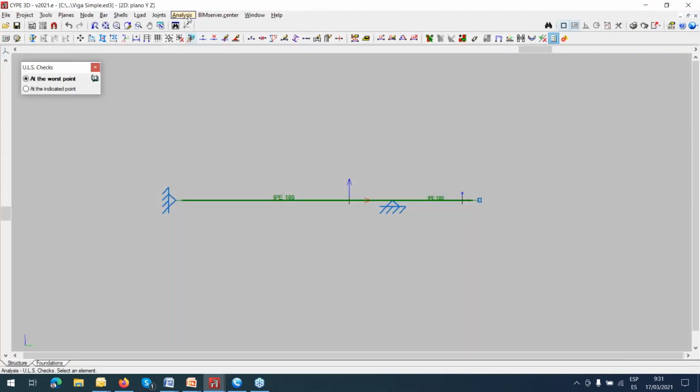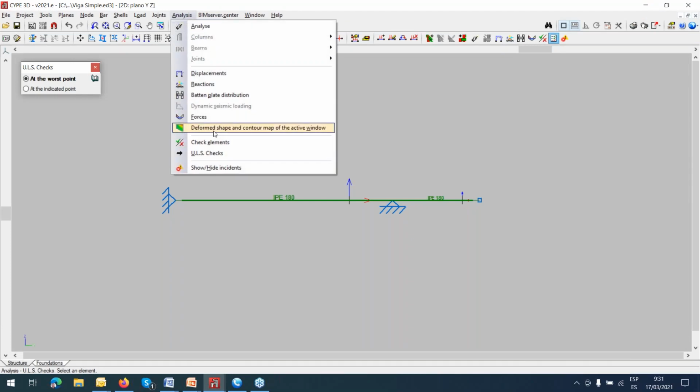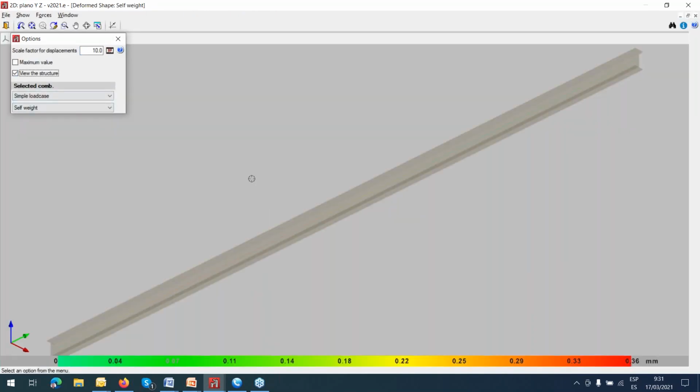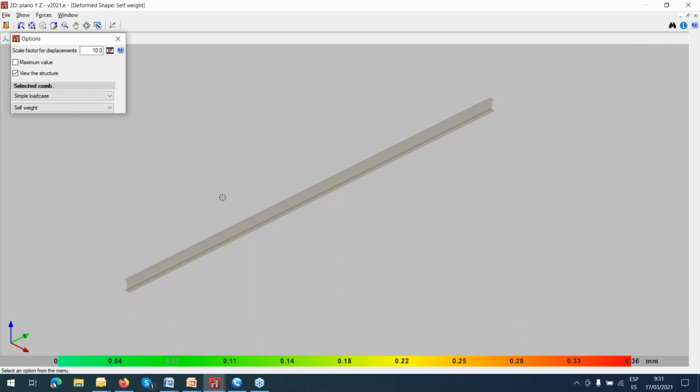And also, for the second analysis, you can visualize the deformation of the bar. And also, I'm going to introduce the profile. I'm going to turn around a little bit, and also the scale, which maybe I'm going to increase by 500. And now on the bottom, you can select the combinations. Could be the sample of cases, could be the displacements, and that's all.